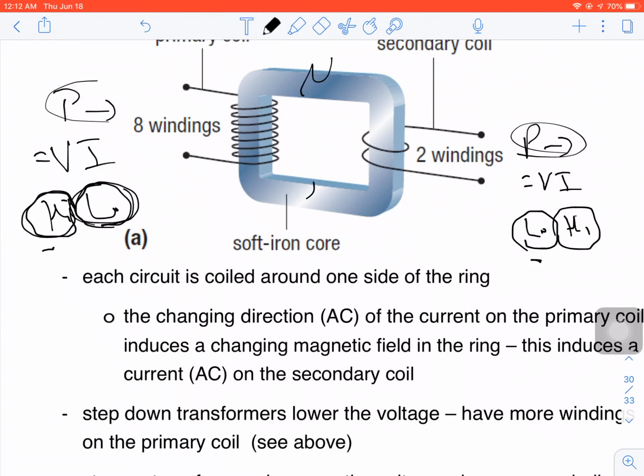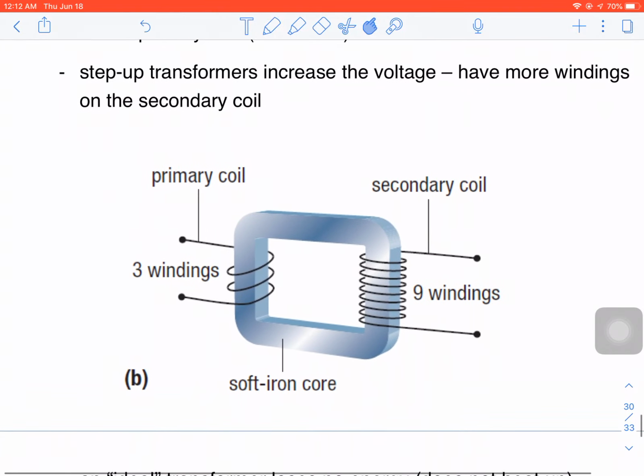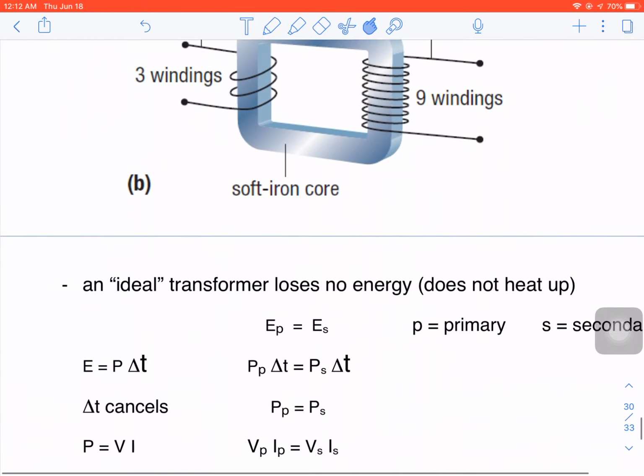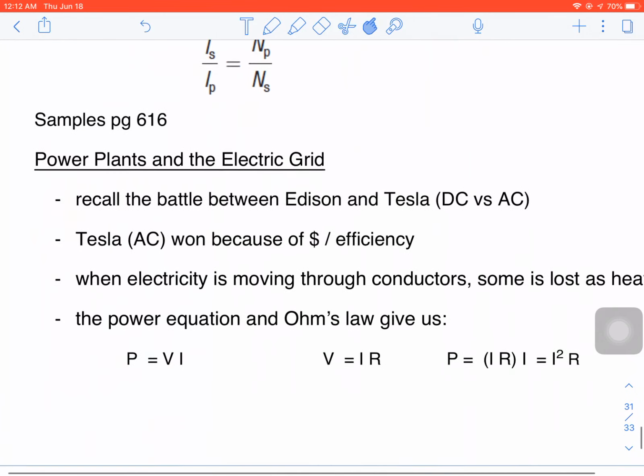It increases the voltage, and then at the other end, here in Hamilton, I've got something called a step-down transformer that takes those really high voltage electrons that are in those overhead wires and drops the voltage down to a safer level, and then spreads them out so they can go to all the different places that they need to go at the other end. So I've got step-up transformers and I have step-down transformers.